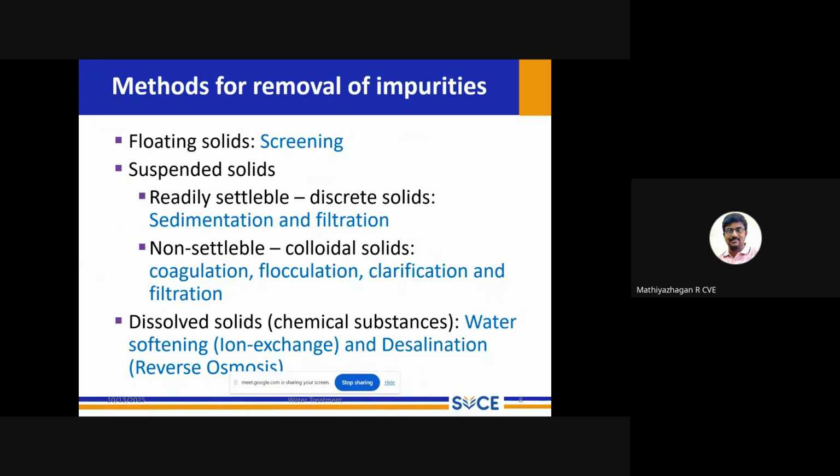The process or the operation is screening. Okay, screening can be used to remove the floatable solids. Yes, for the readily settleable solids, sedimentation and filtration alone are enough, but the colloidal solids create problems. So therefore we go for coagulation, flocculation. Then we move to the sedimentation and filtration process.